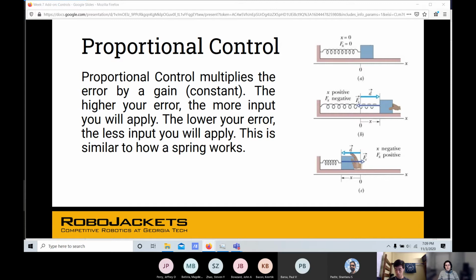So the way that I would like to think about it as well is in that example of the sweltering room that is 100 degrees hotter than you would like. Your heater and your air conditioning are going to want to operate much, much faster when the difference is 100 as opposed to when it's off by 0.1 degrees. It would make no sense to have your heater bounce up and down, trying to get that temperature stable using a constant gain with respect to error, if that makes sense.